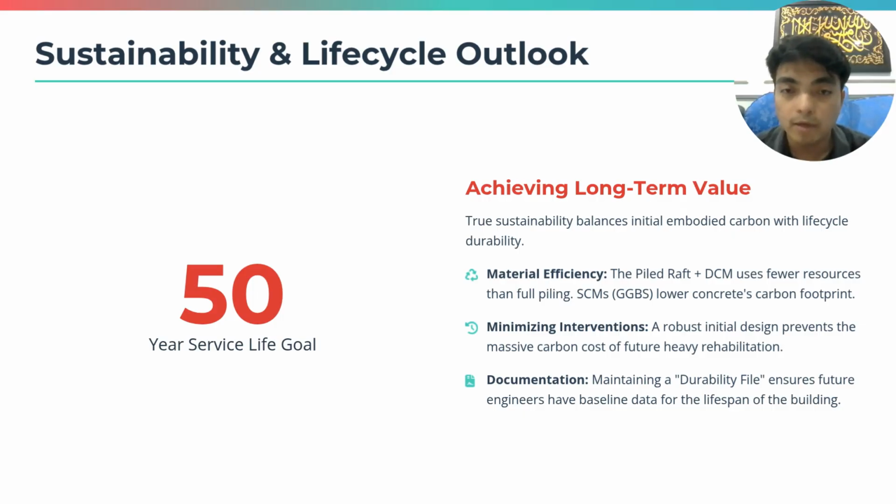By using the piled raft plus DCM approach, we minimize the quantity of bored piles, directly lowering the carbon footprint. Furthermore, we've prepared a rehabilitation workflow. If a defect is detected, we follow a diagnose, stabilize, repair, protect sequence. So we don't just patch cracks, we identify the root cause.